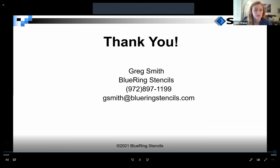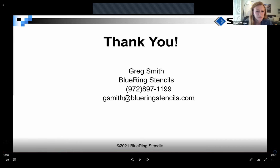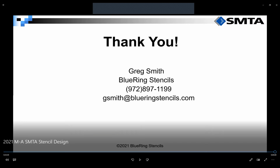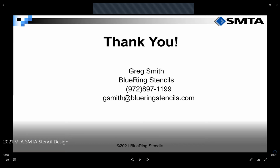All right. In the step down process, what are the squeegee's requirements, metal or rubber? Typically, I would say most customers are using standard metal squeegee blades for doing a 1 or 2 mil step down with no problem.